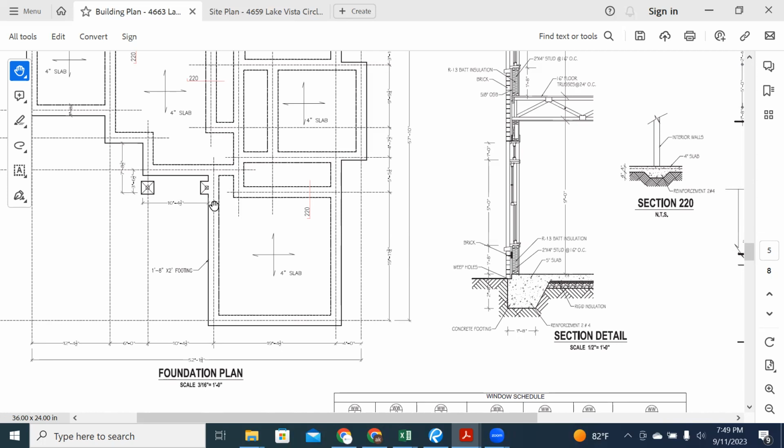It's interesting because I seen a house, it was a rehab house, it's a while ago. I've seen a house where they actually poured everything the same level. It was a bad mistake, rookie mistake, because now they have to cut stuff out and bust stuff out and try to redo it, you know. But if it rains, you can just imagine there's nowhere for the water to stop. So when it rains outside, it's going to just flow right up under your framing and go right up into your house. You know, there's nothing to break that up.